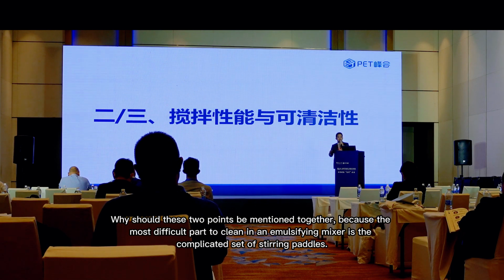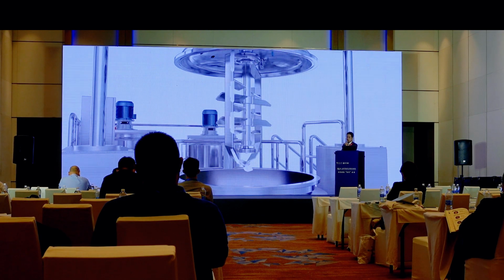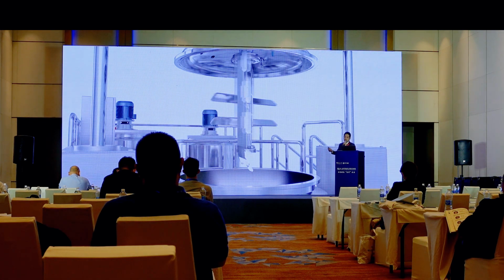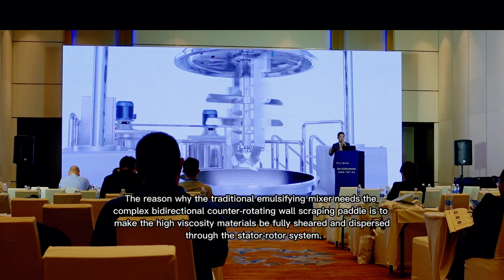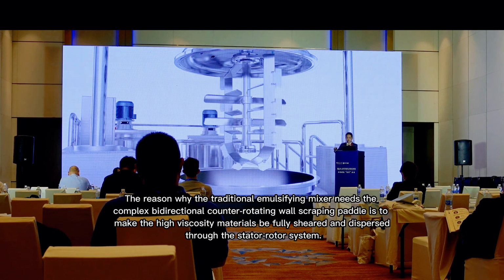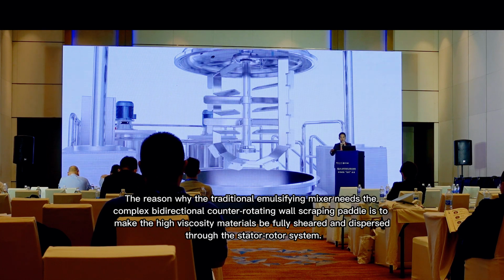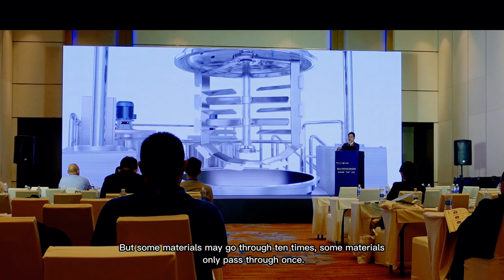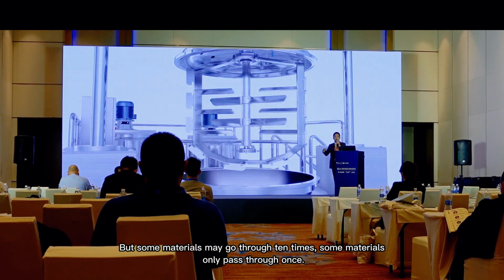Because the most difficult part to clean in an emulsifying mixer is the complicated set of stirring paddles. The reason why the traditional emulsifying mixer needs the complex bidirectional counter-rotating wall scraping paddle is to make the high viscosity materials flow. But some materials may go through the homogenizer 10 times, some materials only pass through once.